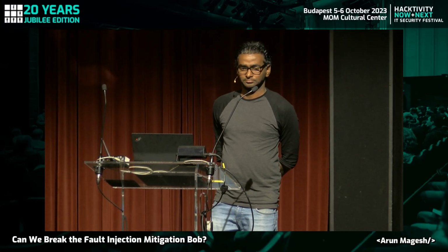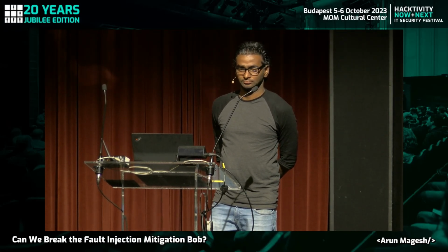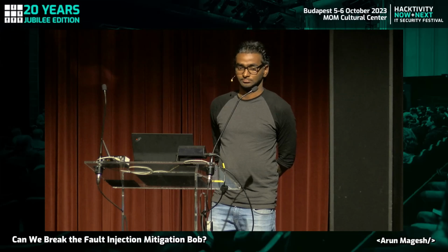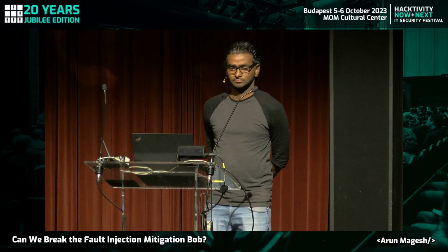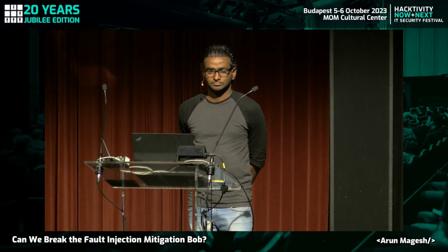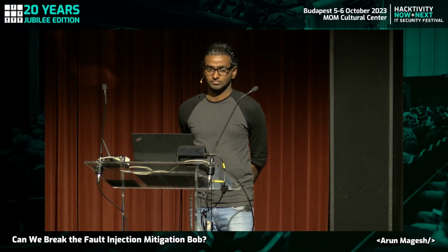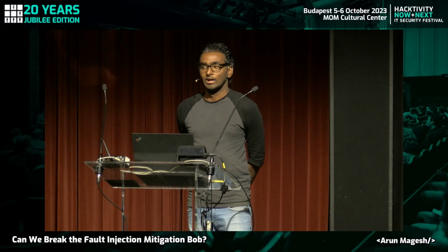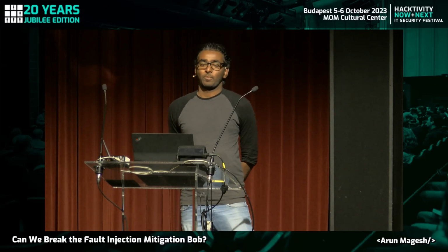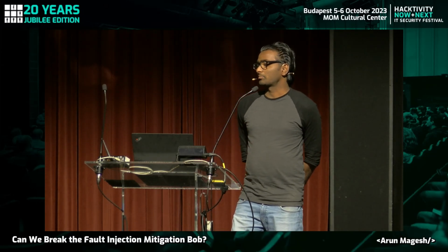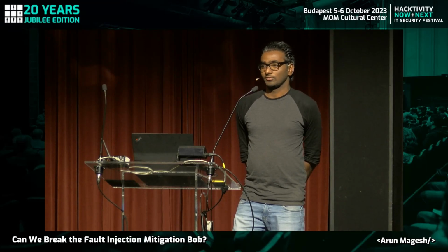So I suppose after you glitch, you analyze the response to see if you have glitched the correct instruction. And I suppose then for the next trial, you reboot the system under test. So this means that to run this kind of test many times, yes, you have to account for the reboot time. Some of these attacks are not persistent, which means if you reboot it, it goes back to the original state.